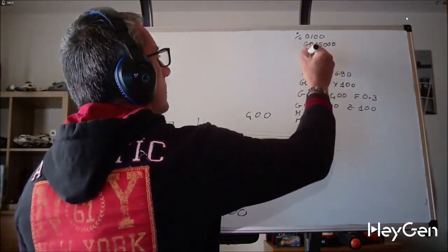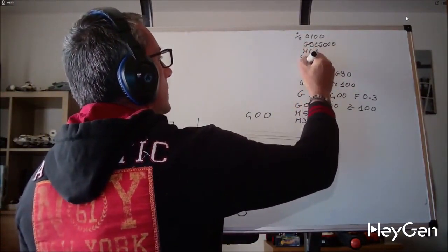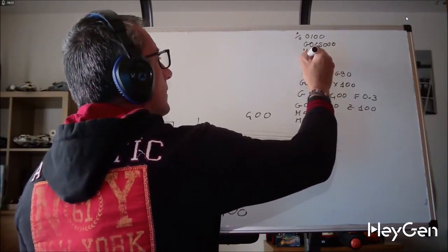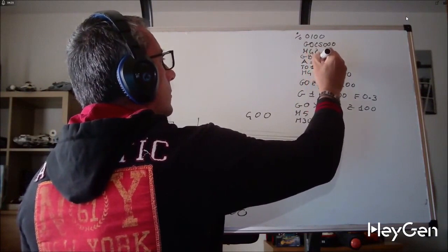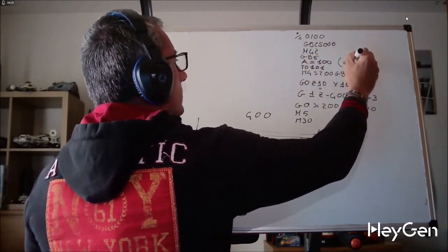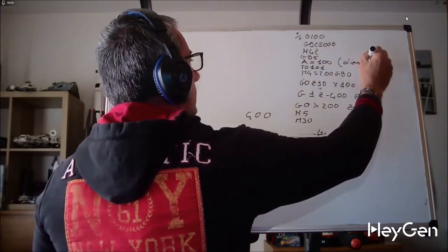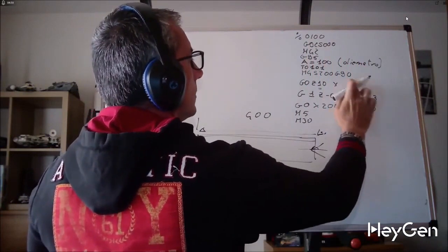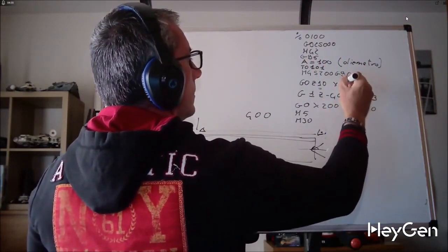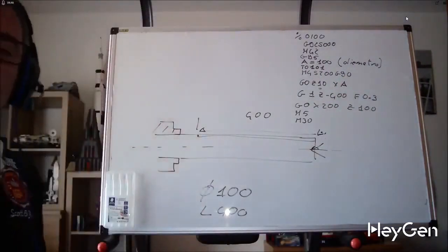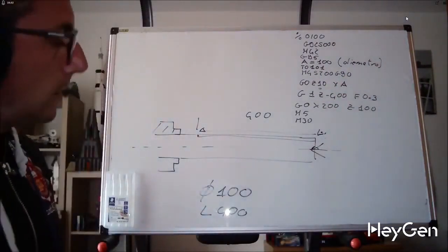If I left a space, it was better. G95 T0. Insert a variable here, and simply say A equals 100 for the diameter, and indicate X not as a numerical value, but as a letter, specifically the letter A. Change to 105. X becomes 105.